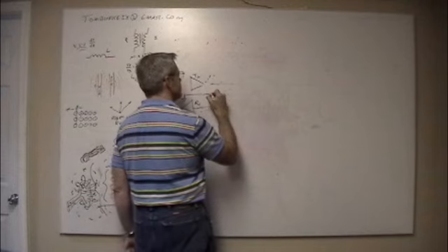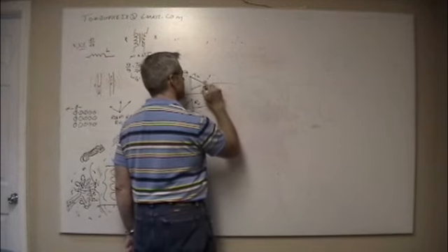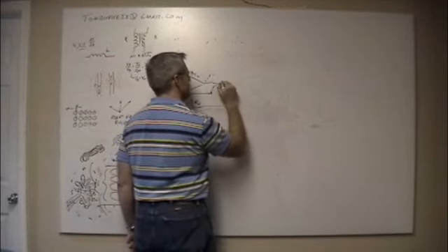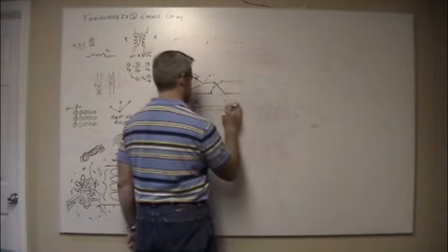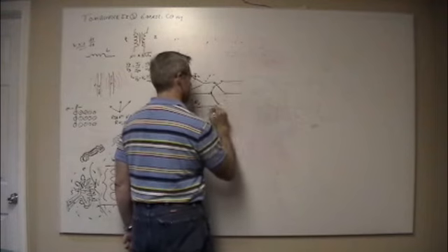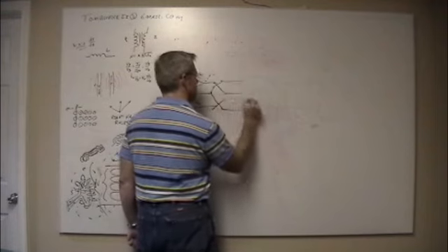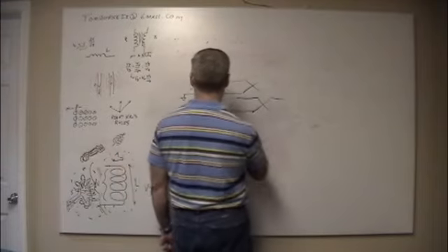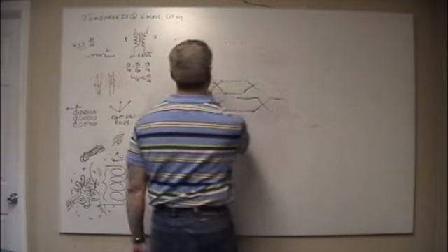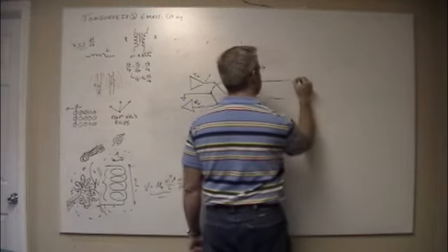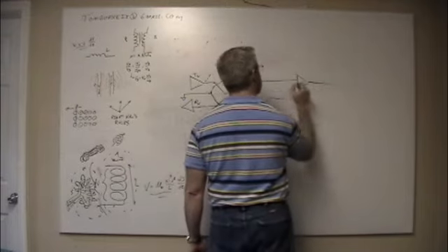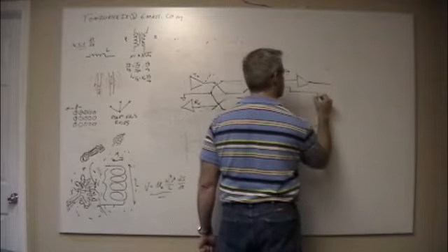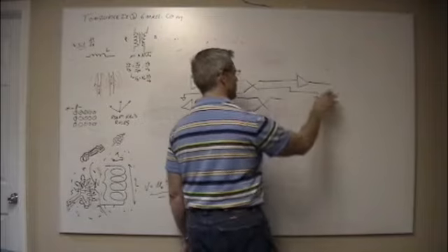What you should do is branch this out and twist them with an individual ground, so two twisted pairs. So essentially, you end up with a common neutral, right, and twist individually with it. And you should do a number like that.